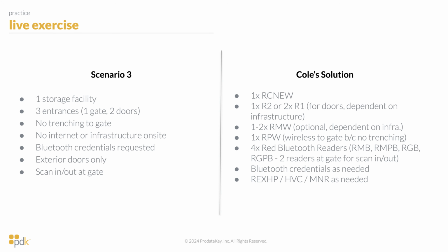Don't forget, range test kits. This one we're using wireless, so range test from the cloud node out to the gate. It's especially applicable with buildings like this where they may be made of cinder block or steel or cement or some sort of plaster, something that's hard for a wireless signal to get through. You really need to take care that you test the wireless environment first.